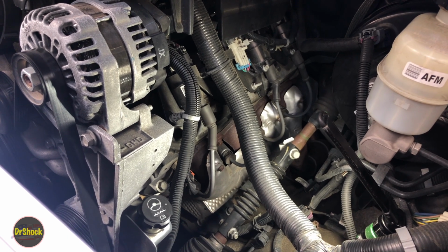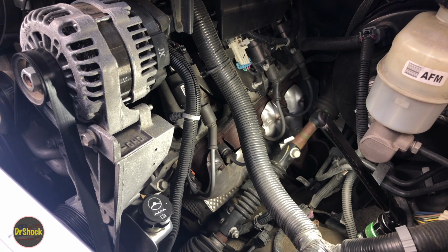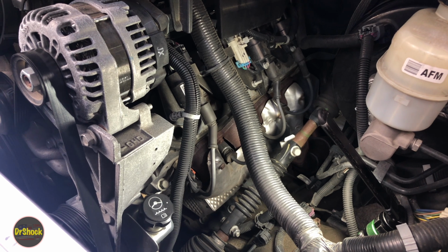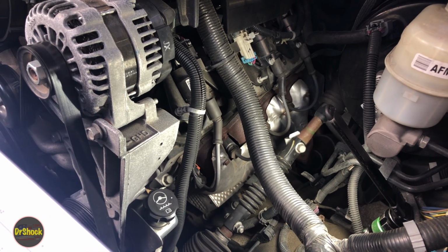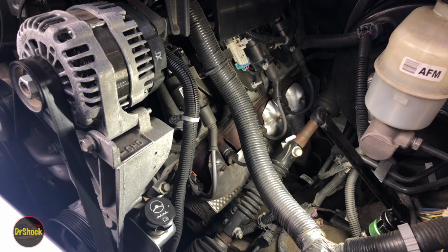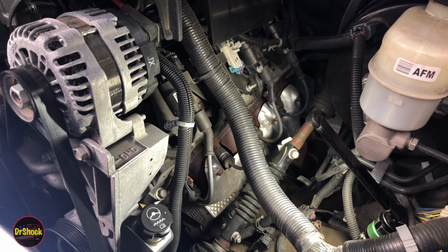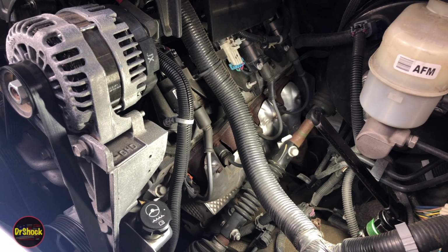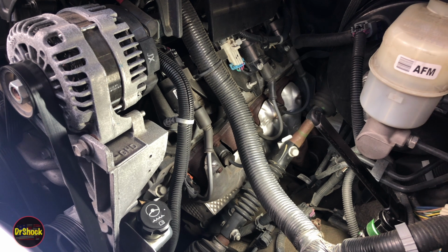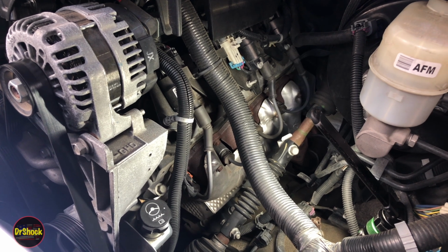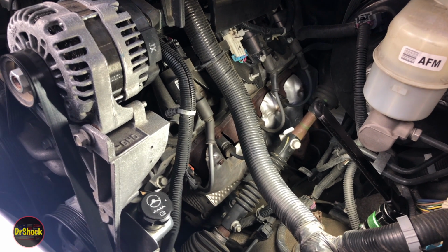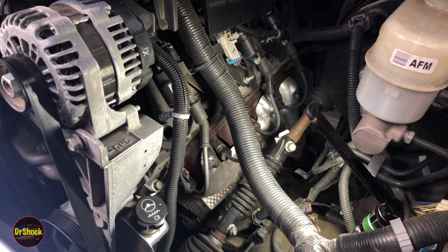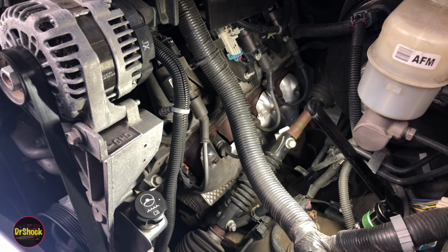Unless you disabled active fuel management in the first couple of years of the vehicle's life while it was still under warranty, the damage to the piston rings is relatively permanent. The only real fix on these 5.3 liters for this oil burning problem is new piston rings. Regardless of what anybody tells you, that's coming straight from engineering at GM, right? That you need new piston rings. That's the only way to stop it from burning oil. So as long as it's burning oil, you're going to have problems like this.